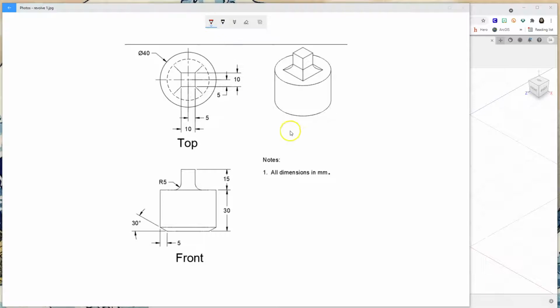In this video, we will be drawing this figure to the right. And instead of using the usual press pull command that we've been using, we will use the Revolve tool. And at the same time, we will be adding fillets. So we'll use fillets and also use chamfer. The fillets can be seen here. And then the chamfer could be seen down here.